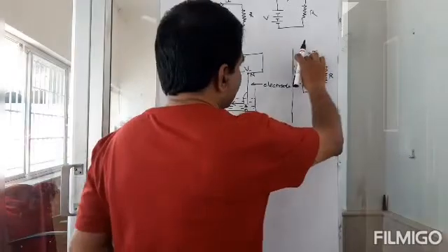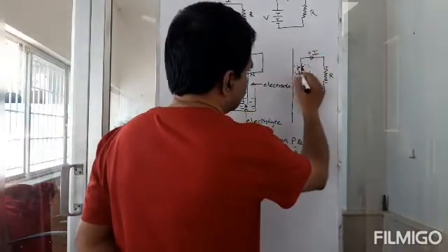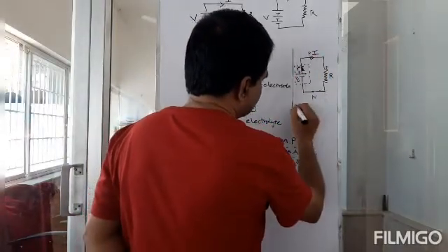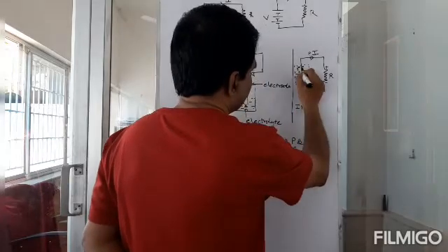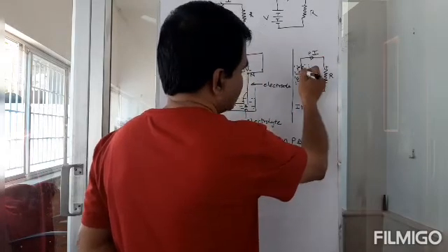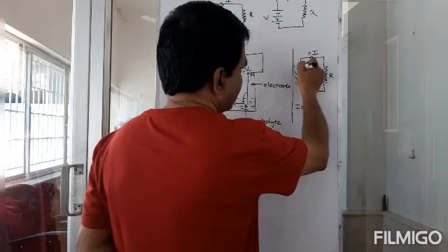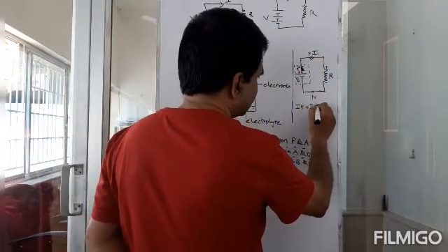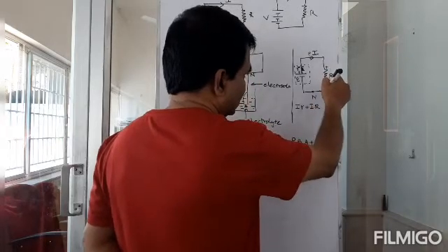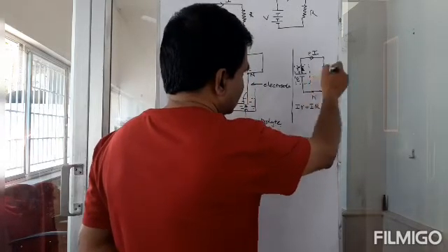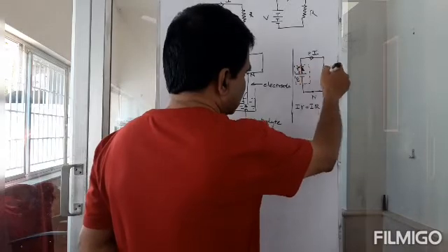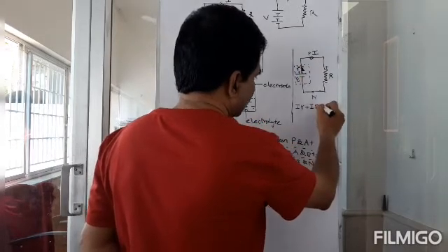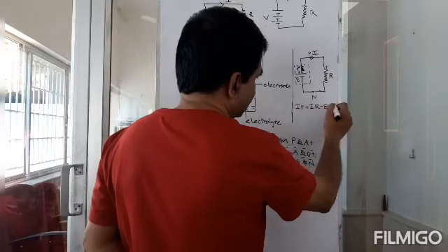So what is the potential drop here? I into r. I'm entering here, so it's going to be I into this small r. I'll start from here and I'll come back to the same position. So Ir is a potential drop here, and then I into capital R is a potential drop here, and then I come here. See, I'm entering it here, plus, here it is minus, so minus E, epsilon is equal to 0.